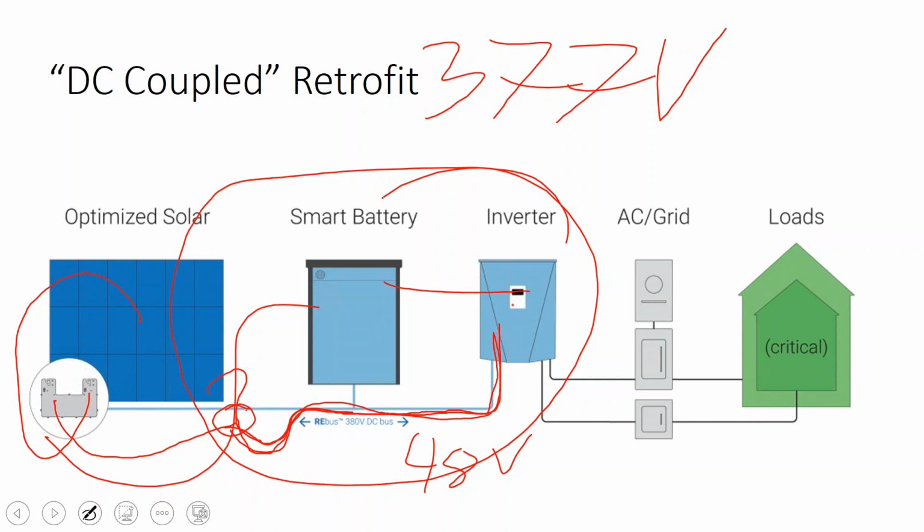And actually, a lot of the battery inverter manufacturers want to sell you the accessories that say, look, you're going to need an AC service panel for connecting to your loads, and you're going to need a DC service panel for wiring up the batteries to the solar array, to the battery inverter. They'll usually sell you a service panel that can combine all of those functions, where you'll have a separate DC side and a separate AC side. That's kind of exciting that we're actually getting into DC panels and some DC output.